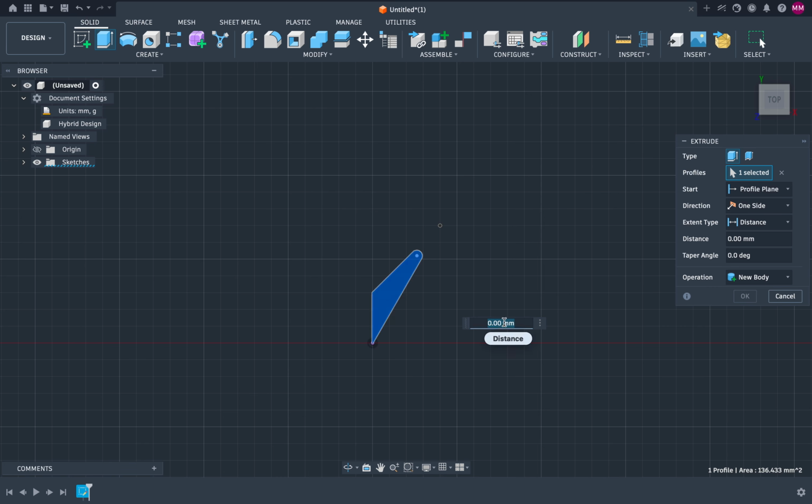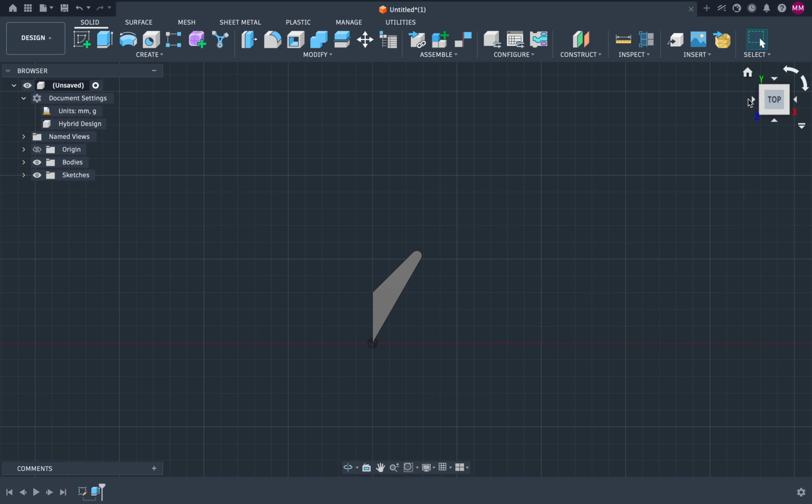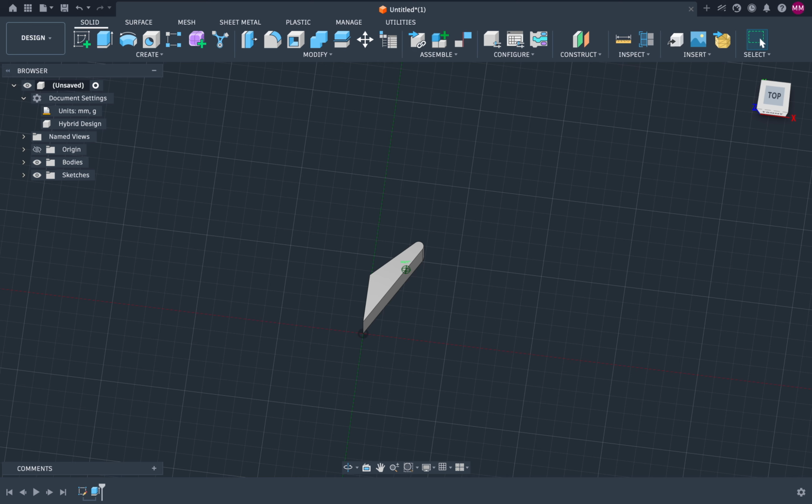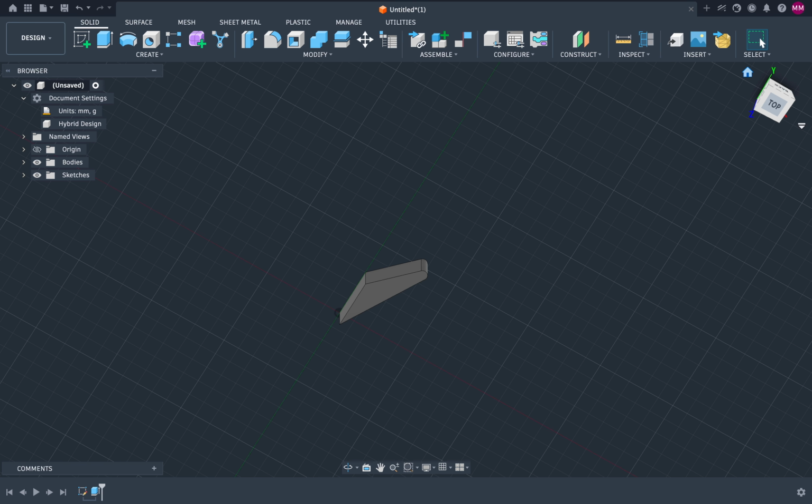And now we want to extrude it by a certain amount of millimeters that would still be comfortable to put your clothes on, but we also need the place for the screw, right, to screw it into the wall. So let's just extrude it just a bit, about 10 millimeters, plus it will add durability, since we are not making it out of metal, we're making it out of PLA, most likely. And here we go.